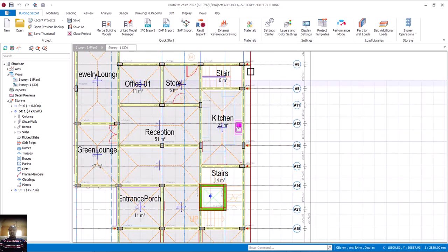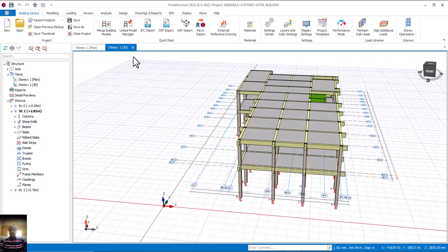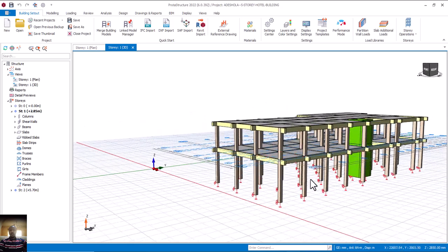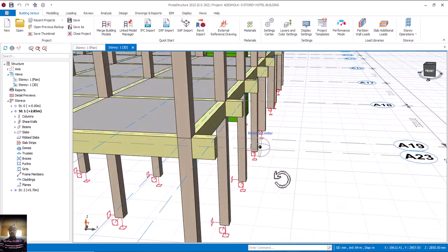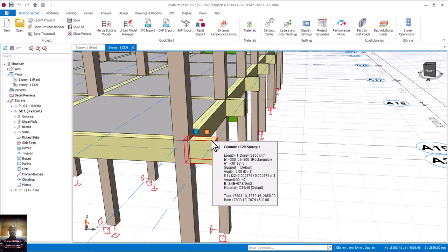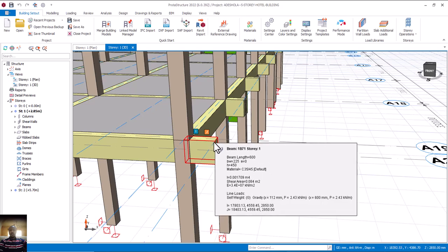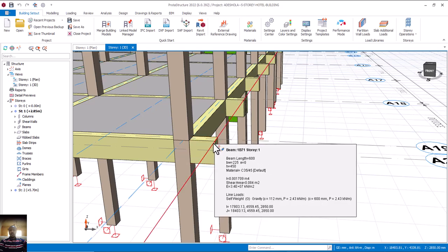From this story 1, let me put my beam along this side. I want to put a beam in the sense that, let me show you something. If I put only slab on this place, are you getting me? During construction, definitely as it is, this one cannot pass the design, because this is 450. I'm still expecting something bigger than this, maybe something like 650 or 750.